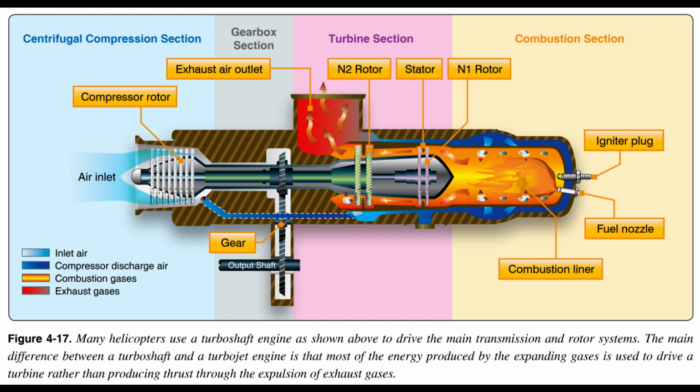Compressor. The compressor may consist of an axial compressor, a centrifugal compressor, or combination of the two. An axial compressor consists of two main elements, the rotor and the stator. The rotor consists of a number of blades fixed on a rotating spindle and resembles a fan. As the rotor turns, air is drawn inward. Stator vanes are arranged in fixed rows between the rotor blades and act as a diffuser at each stage to decrease air velocity and increase air pressure. There may be a number of rows of rotor blades and stator vanes. Each row constitutes a pressure stage, and the number of stages depends on the amount of air and pressure rise required for the particular engine.